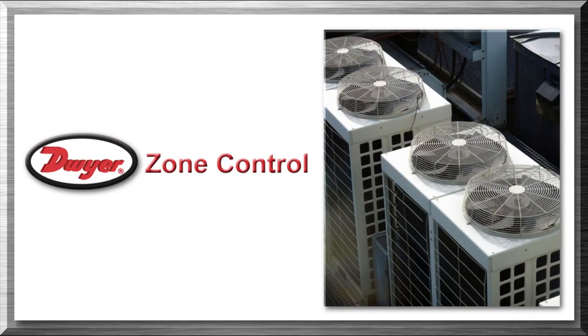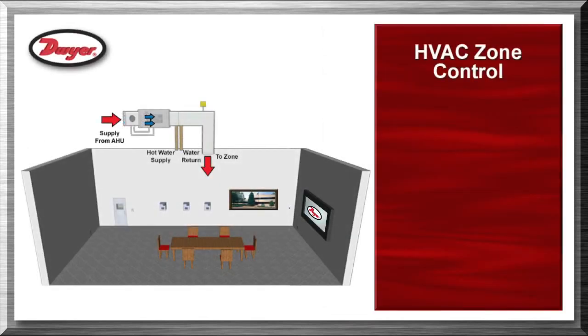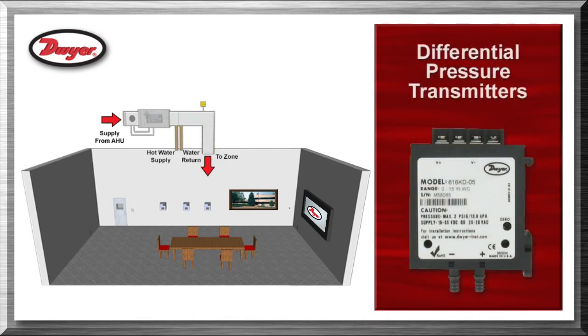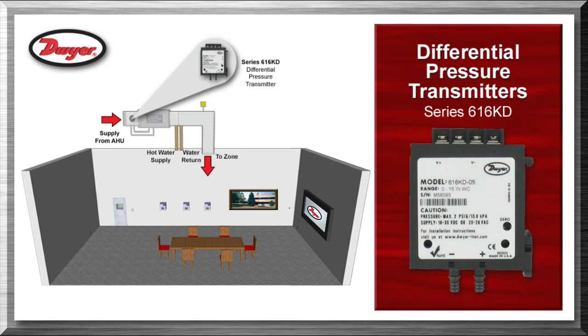Zone control. Buildings are often broken down into zones for better control of the HVAC system. These zones can have variable air volume, or VAV, systems with a terminal unit, often called a VAV box. A VAV terminal unit controls the airflow into the zone, thereby controlling the environment of the zone. Differential pressure transmitters, series 616KD, are used to monitor the duct airflow rate. The amount of airflow to the zone is changed according to the demand.